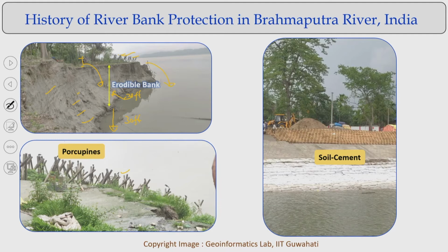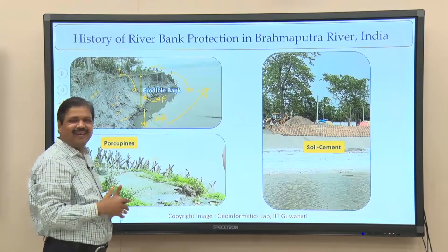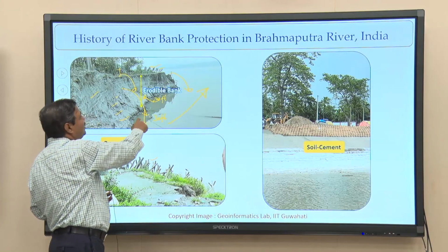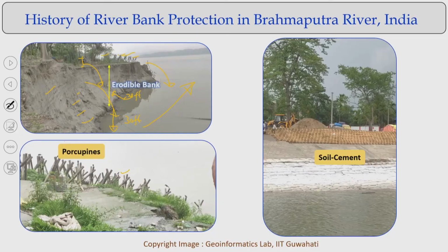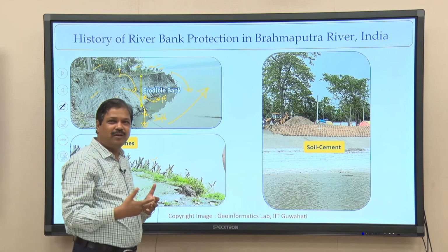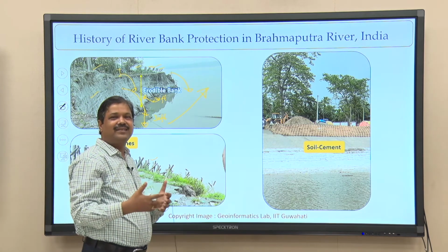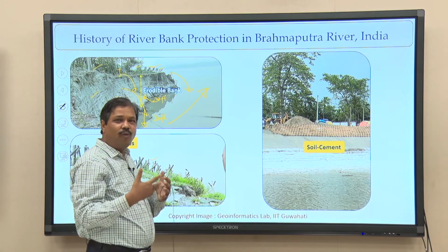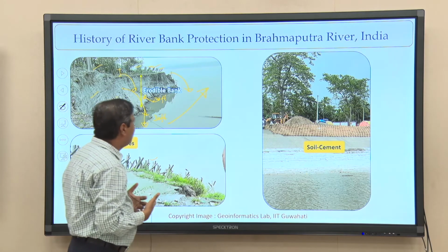You can see how dynamically the erosion processes happen: the toe materials are eroding instantly and collapsing the bank materials, while at the top the protection and trees are still standing. The bank erosion process in the Brahmaputra happens at a scale that does not occur in many parts of the world. So, we should try to understand what types of bank erosion processes are happening.